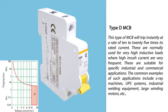Type D of miniature circuit breaker. This type will trip instantly at a rate of 10 to 25 times its rated current. These are normally used for very high inductive loads, where high inrush current are very frequent. These are suitable for specific industrial and commercial applications. The common examples of such applications include X-ray machines, UPS systems, industrial welding equipment, large winding motors, etc.